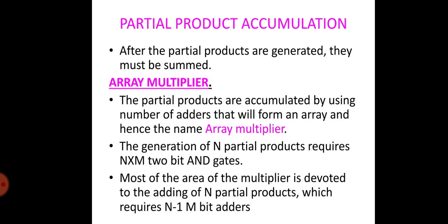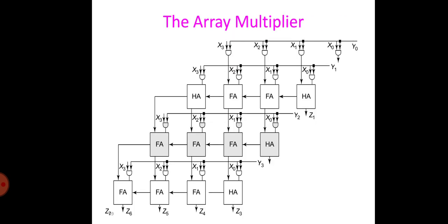Due to the array organization, determining the propagation delay of the circuit is not straightforward. You can consider this implementation where the partial sum adders are implemented as ripple carry structures. Performance optimization requires that the critical timing path be identified first. This turns out to be non-trivial, and in fact a large number of paths of almost identical length can be identified. Two of those are highlighted here.